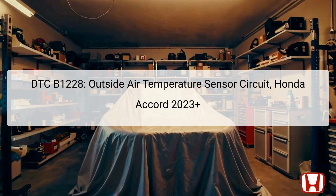The outside air temperature sensor plays a vital role in helping the climate control system regulate the cabin temperature based on external atmospheric conditions. Located usually in the front grille or near the front bumper, this sensor monitors the ambient air temperature. When malfunctioning, this can negatively impact cabin temperature control and comfort.